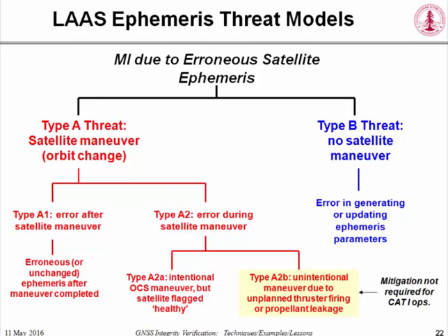So I'll talk a little bit about ephemeris faults. Again, these were considered to be very rare back when we built the original threat model, because we knew clock failures were much more frequent. Now clock failures are infrequent, and at least two examples of ephemeris failures have occurred in the last 10 years. Still rare, but not rare enough that we can ignore them.